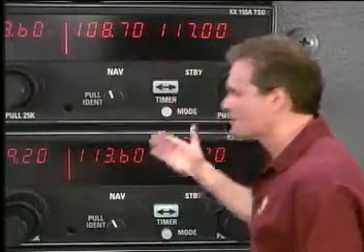If your self-briefing for the ILS approach at Ellis Airport in Jacksonville, North Carolina was your dress rehearsal, then think of setting up for the approach as preparing the stage for your grand performance. When you set up for an approach, you not only want to tune in and set up every radio you'll need in the approach, but you also want to set in backups where possible and make sure every radio is doing something, that nothing in your avionics arsenal gets a free ride. Having all your radios set up early means you'll have fewer tasks and distractions during the approach itself.